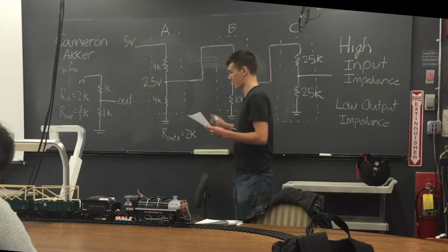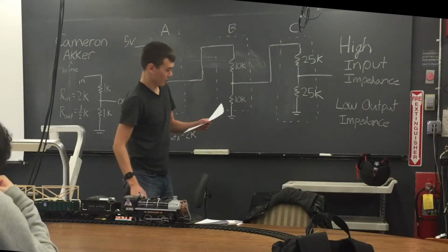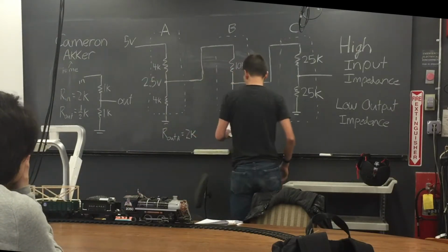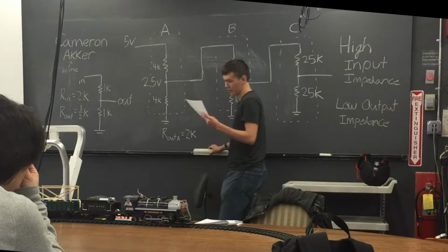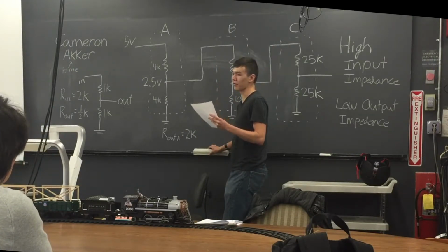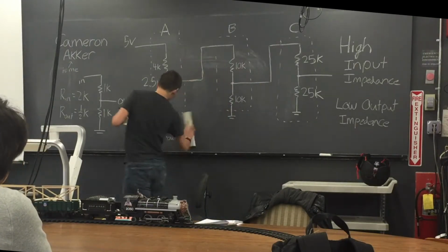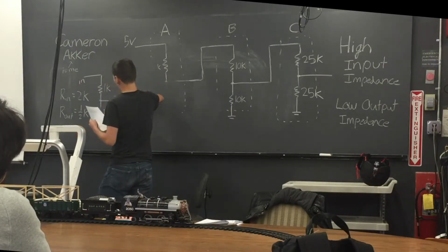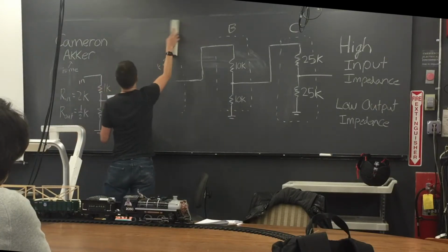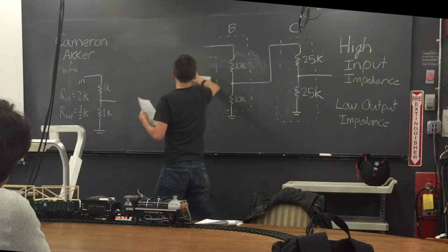Okay, so there's 2 stages. I'm going to erase all this and put this up there real quick. The most important part is your load is high input impedance from the look of it. It's just drawn as a resistor. What that means is you need to have low output impedance for your middle stage, but you also want it to be higher than that first stage.